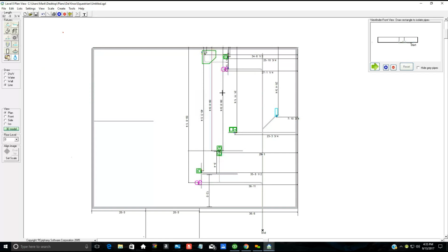It'll turn red when you hover over it. And that's the center. That's to the center of each stack for every fixture. Which is what you want when you're doing concrete plumbing. And so you can send this out to the guys in the field, and they should have no excuse for not getting those stacks exactly where they need to be.